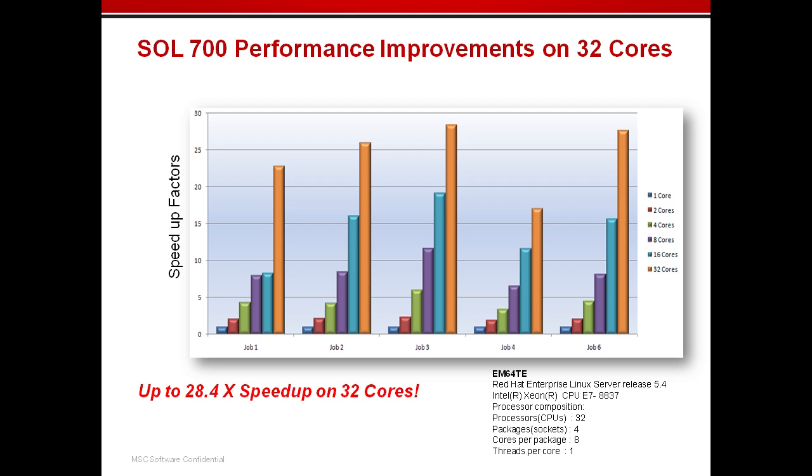This is a cleaner chart which shows you the performance of MSC Nastran 2013 and the speed up factors. Again, we had very good performance improvements for large models and complex, CPU-intensive applications like hydroplaning, glass flushing, and other large FSI applications. Overall, the performance improvements for Nastran 2013 were up to 63% on single core and up to 133% on 64 cores compared to the previous version, 2012.2.